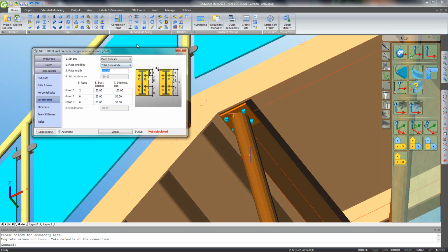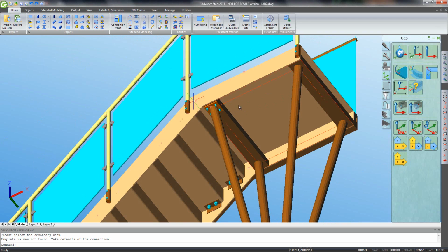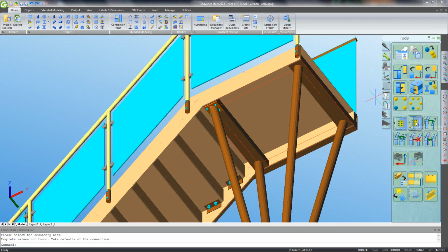Okay, that looks good. So having got one joint now how I like it, I can use our standard copying tools to copy the whole joint with that configuration I've just created to multiple locations. So at the top of those 3 legs, just like that. And there you go. Got the 3 new joints added in, taking into account the angles and miters in each position correctly.